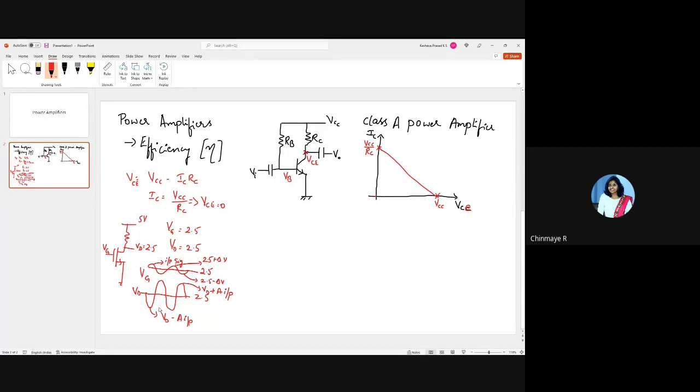Are you all able to understand this? Now what happens if I put this at 3 volts? So this can only go up to 5. Therefore, the swing will be just plus or minus 2 volts, right? Because maximum it can go only up to 5. So if I make the DC voltage of this the average of 5 and 0, then I get the maximum swing. Correct?